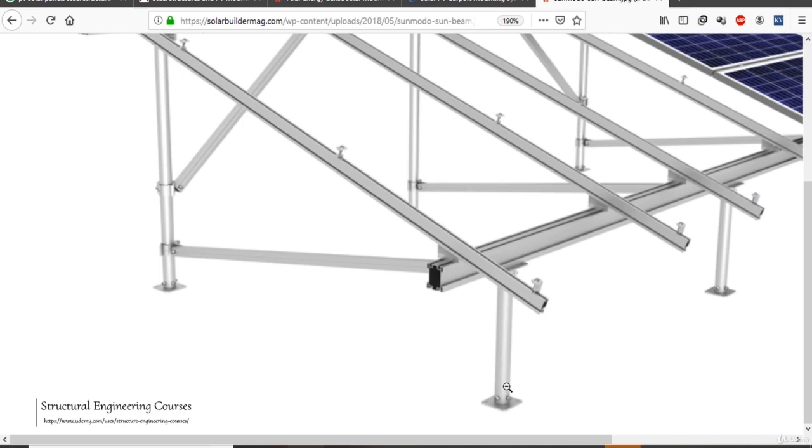And you must be thinking why we use this type of arrangement in the light poles also. Because in both the directions the forces are the same, so the section modulus required for the structural steel sections is also the same. To have the most economical and the most efficient section, that is why we use circular sections for the light poles also.